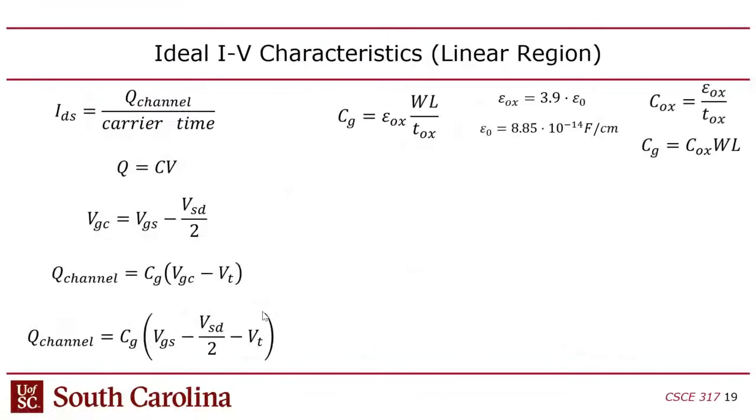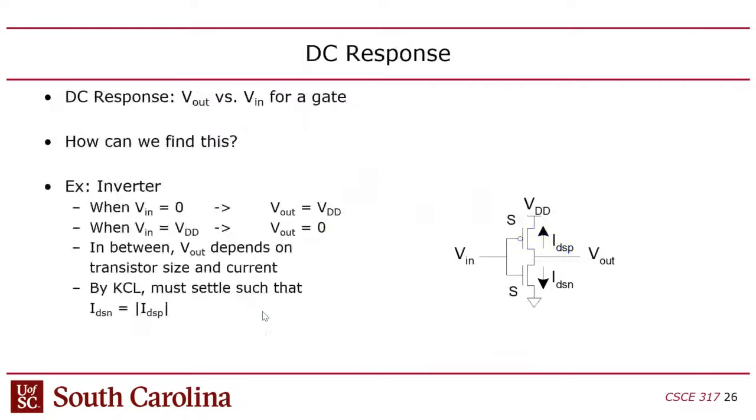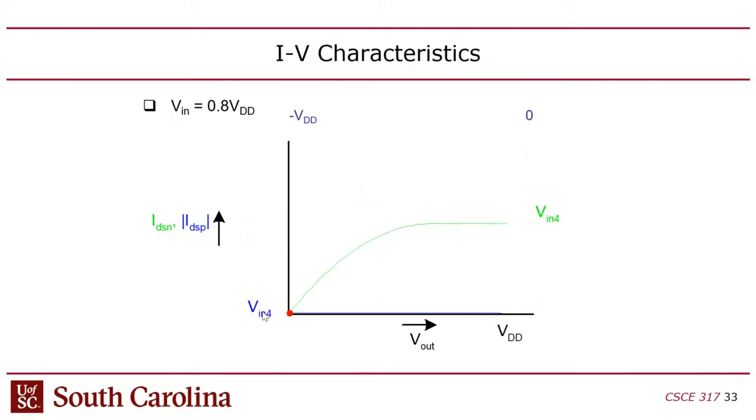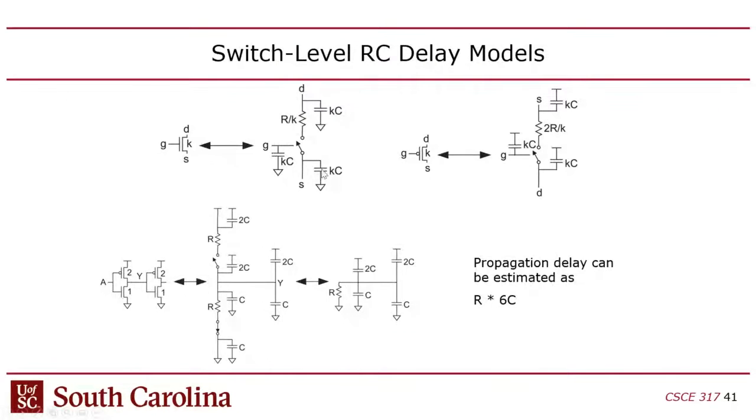So you might say, who cares if it's connected to ground? What's the significance? Well, if the source is connected to ground, then you can disregard that capacitor. This capacitor wouldn't do anything if both sides of it were grounded, right? So keep that in mind. The capacitor only contributes if at least one side is not grounded. Makes sense?